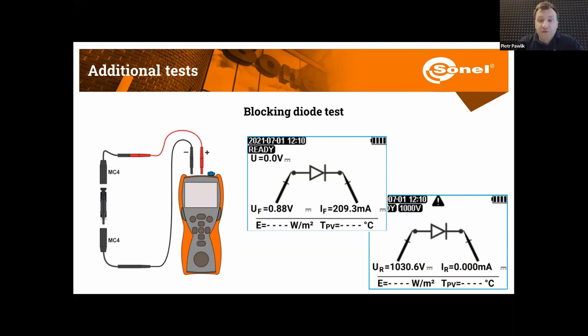In normal operating mode, the voltage across the blocking diode shall be measured. The criterion for passing the test is that the voltage across the blocking diode should be between half a volt and 1.65 volts. Where the voltage is outside of this range, the system shall be further investigated to determine if the diode failure is an isolated incident or the result of another fault of the system.